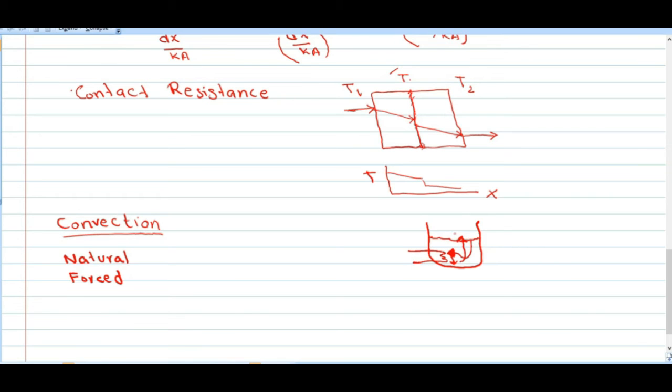In this way, heat transfer occurs because of the density difference and because of the buoyant forces, movement of the molecules occurs. Therefore, molecules leave their original position from the hot surface of the coil to the top colder surface of the liquid. In this way, molecules leave their position and get heated up. This is called natural convection.